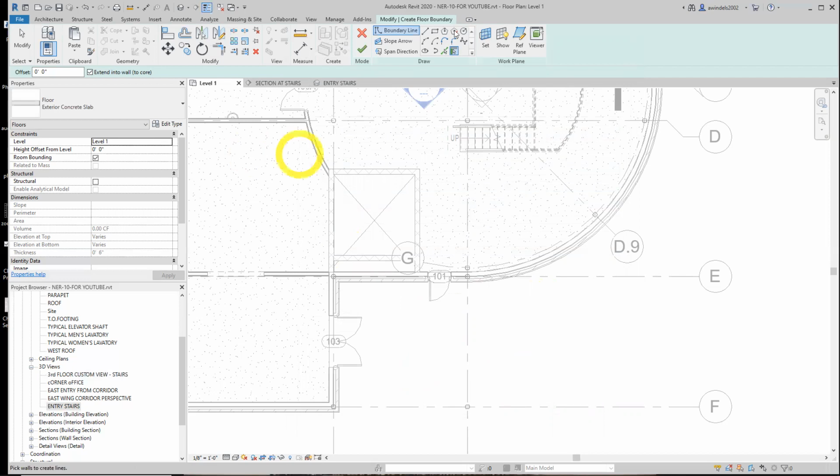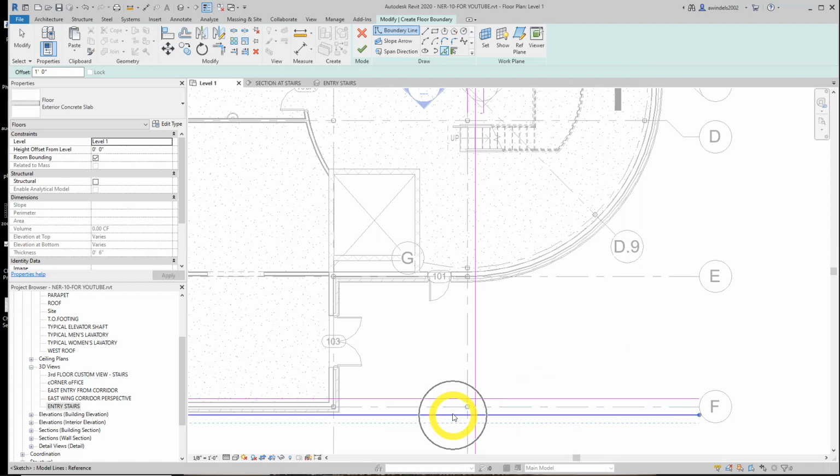Let's go to town on that by doing the pick line. It looks like it's a foot off of the grid lines here and here. So I'm going to say pick line. I'm going to say offset 1 foot. Go with this. Oh, wrong side. Want it on this side. Hit escape. Let's delete. Z, hit escape twice. Delete that. There we go.